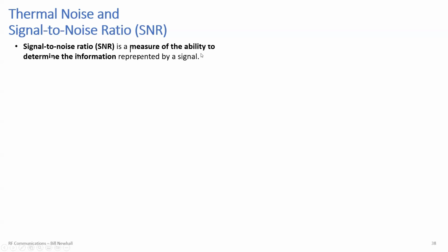If it's a digital system and you're sending data, video, something like that, then based on the type of receiver, you can estimate based on the SNR that makes it to the demodulator what the quality of the data is going to be, how many errors you will get, the bit error rate.